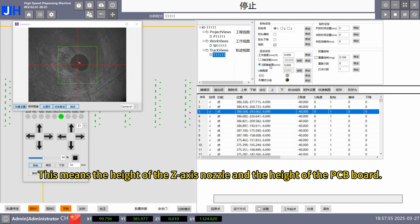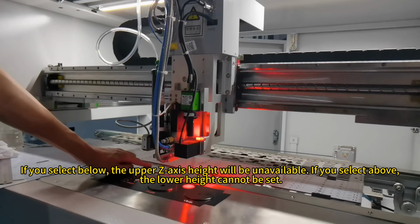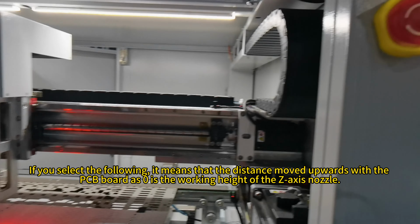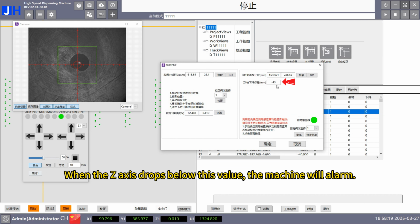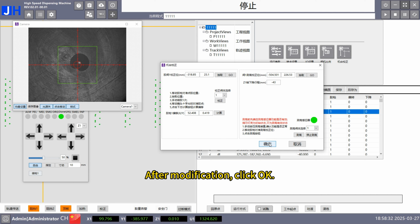This means the height of the Z-axis nozzle and the height of the PCB board. If you select below, the upper Z-axis height will be unavailable. If you select above, the lower height cannot be set. If you select the following, it means that the distance moved upwards with the PCB board as 0 is the working height of the Z-axis nozzle. When the Z-axis drops below this value, the machine will alarm. When we manually lower the workhead, the machine will alarm when the Z-axis drops below this value. After modification, click OK.